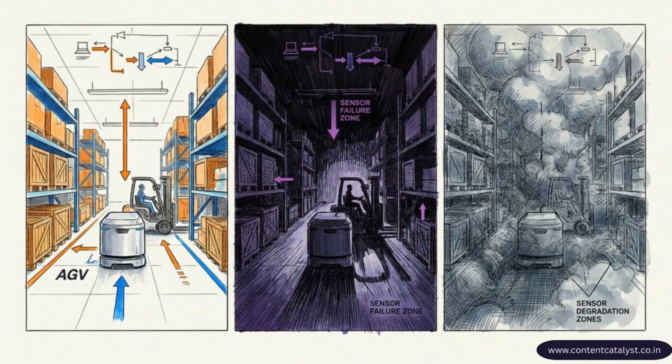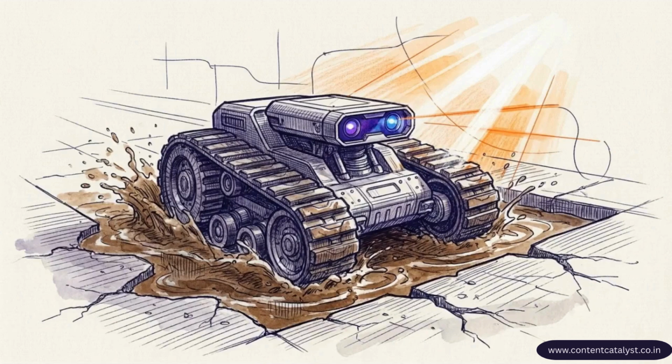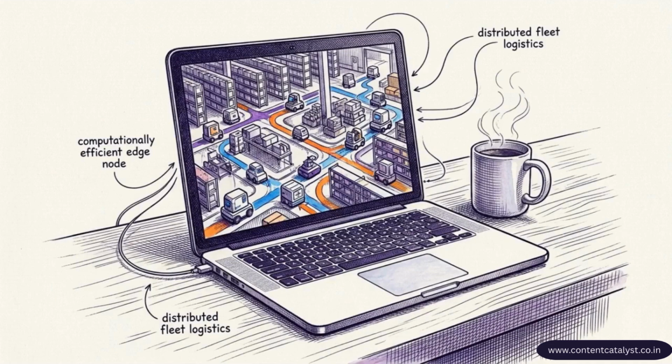Webots supports this scale because it includes highly credible simulation for core inputs like LiDAR, stereoscopic cameras, GPS, and IMUs. The environment becomes a computationally lightweight dataset factory. You can instantly generate severe edge cases, unusual warehouse lighting, occluded sensors, or rare mechanical failures. Generating this specific data synthetically ensures your AI models will survive unexpected physical variables, and it does so without requiring a massive, expensive GPU farm.